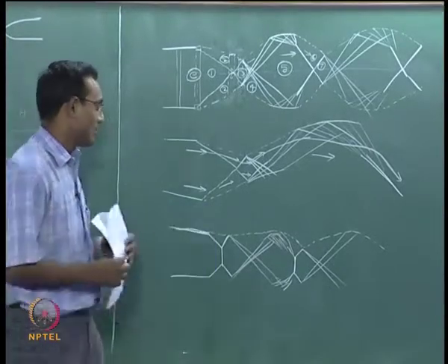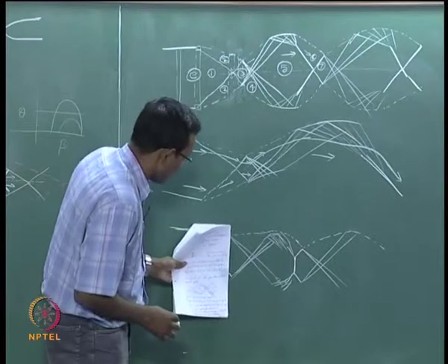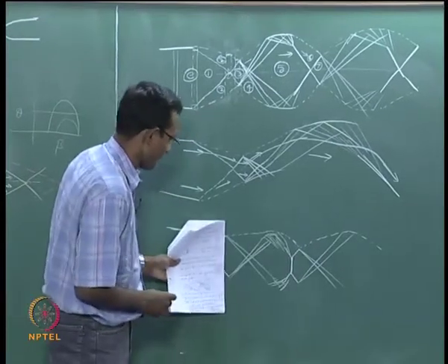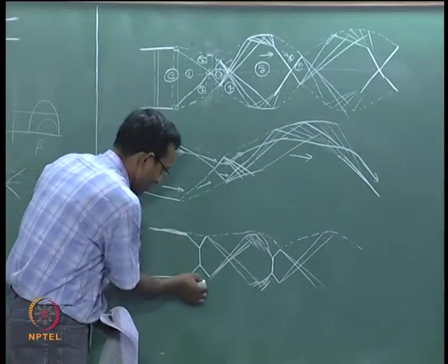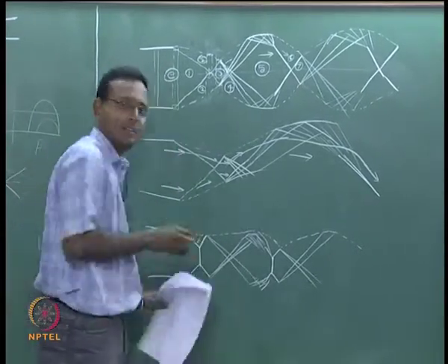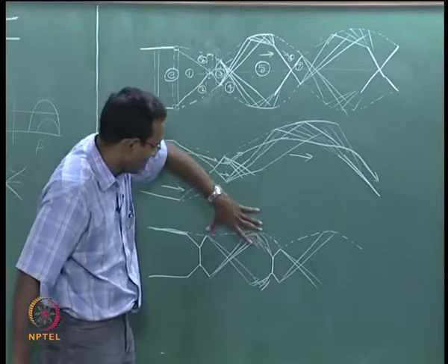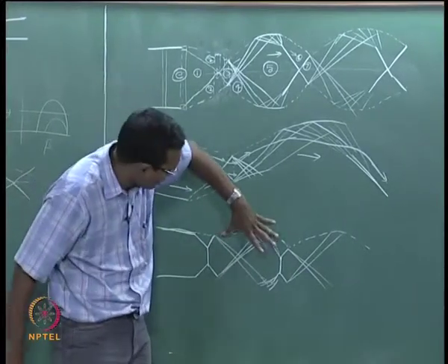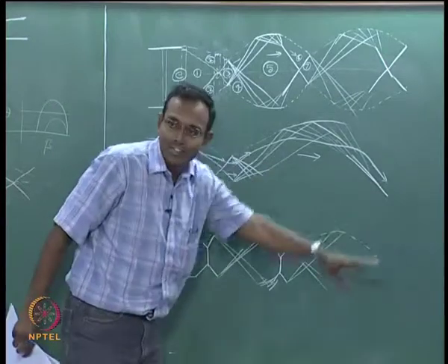So if you look at it again, starting from expansion till the shock, the whole sequence repeats after that. The only thing that does not repeat is the first shock portion. This particular thing is called the expansion shock cell. The same structure repeats again and again. They call it the shock cells.